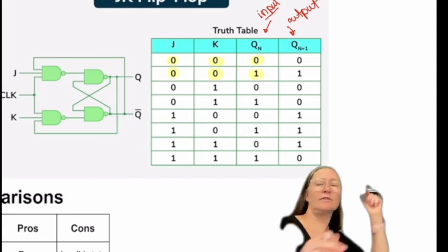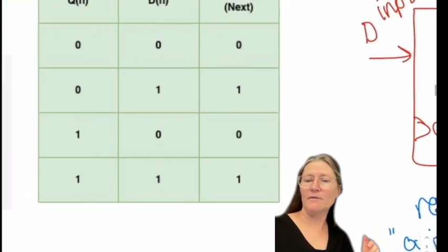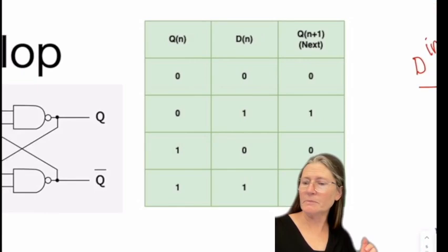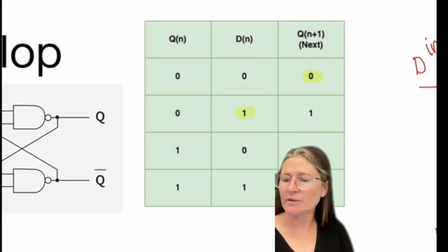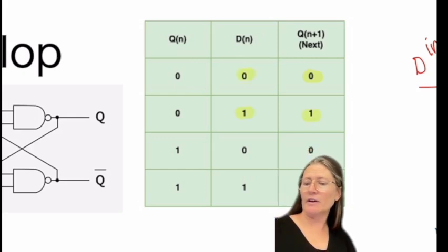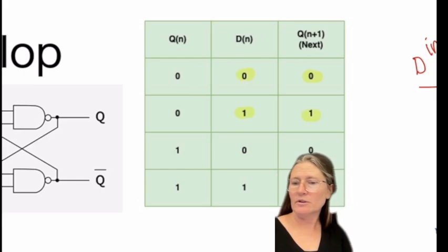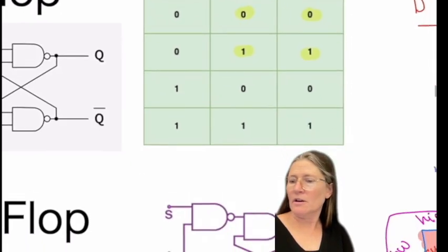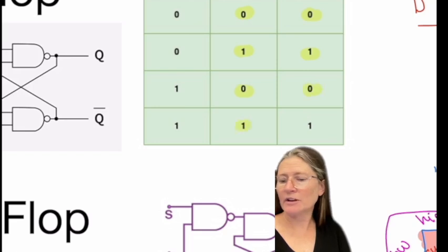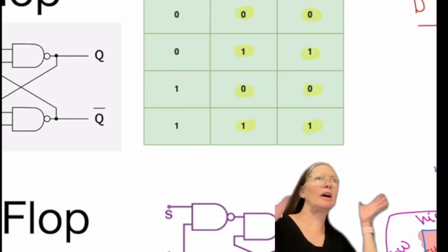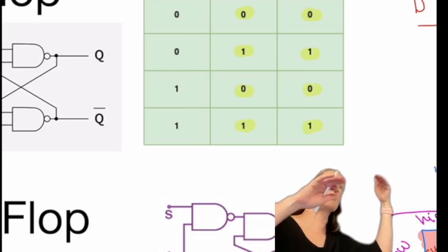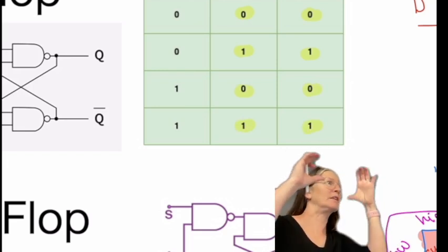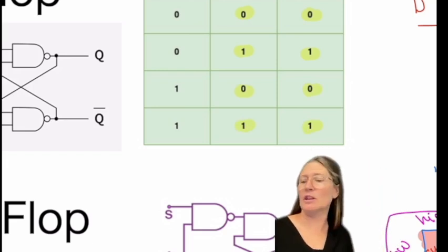So if you have 0 coming in, then your output will be 0 out. If your 1 is in, then you get 1 out. So that one is just simpler, where whatever you have on it, it just kind of puts it into that D flip-flop, and your output will be based on that.